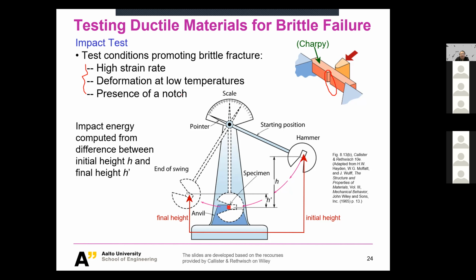And by improving the strength of the material, you will improve the maximum principal stress that is really contributing to the cleavage fracture. And the whole material is becoming very close to that threshold, which is finally reflected as the K1C. You could also think about there's a threshold local strength.